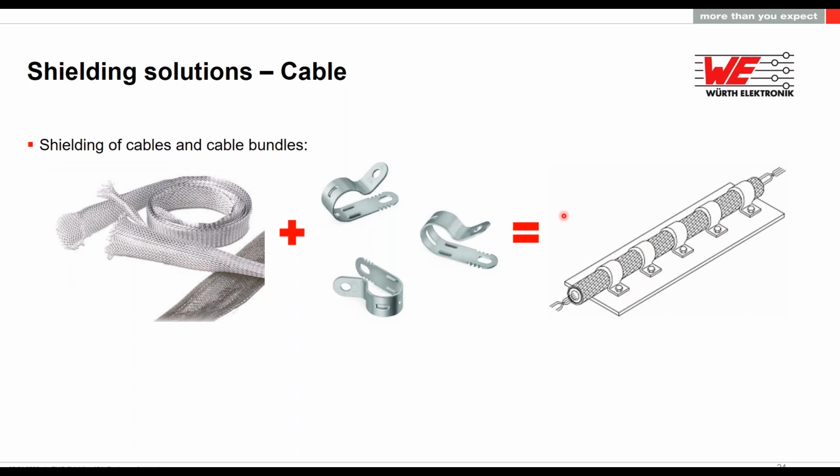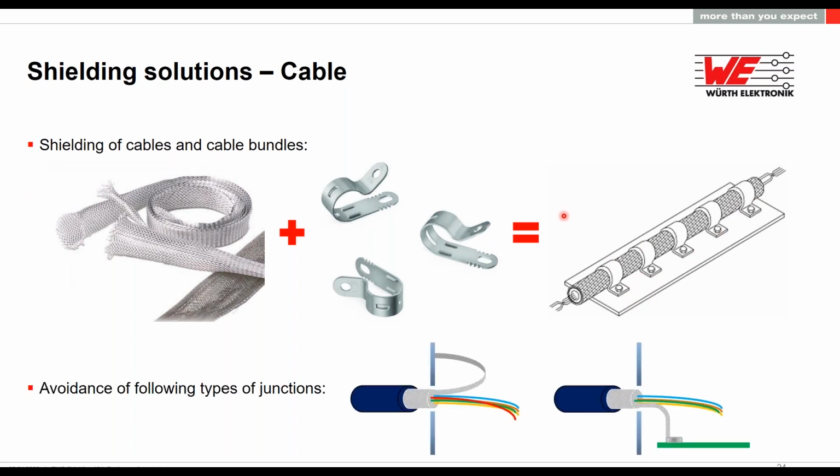What are we preventing with this? The most common kind of connection that I ever seen in customers when they request advice and so on, or engineers in general, are these kind of connections. We have the shielding of the cable and we directly solder it either to the housing or to the ground of the PCB. When we are doing this, we're creating a problem that is called pigtail.